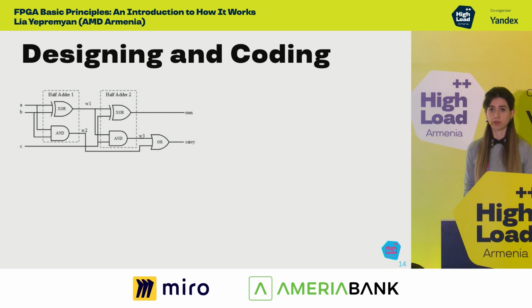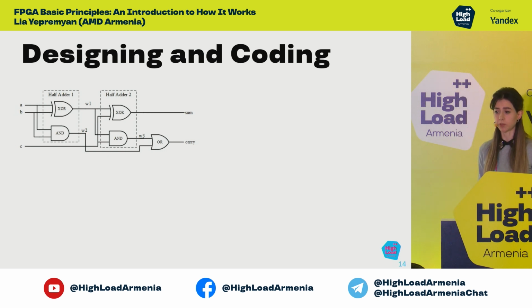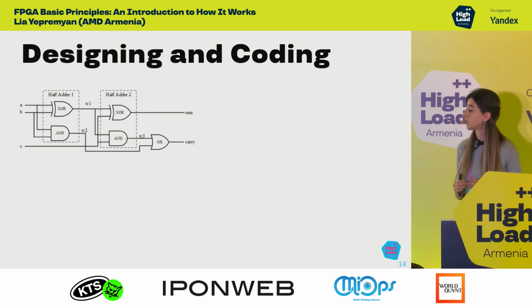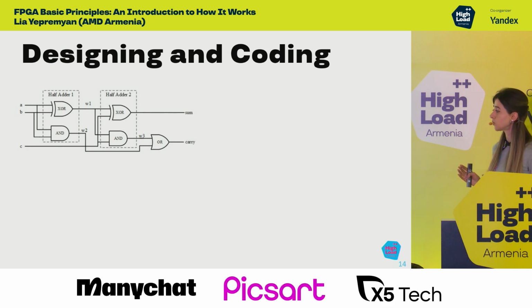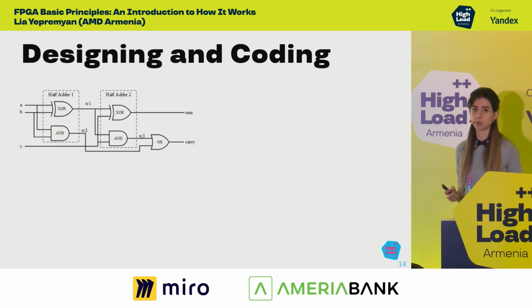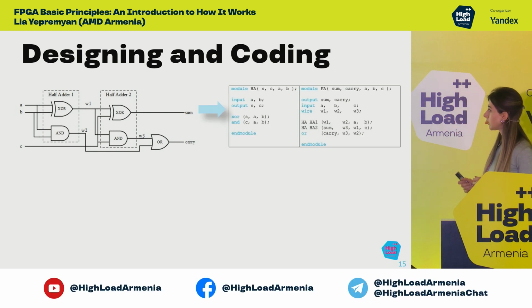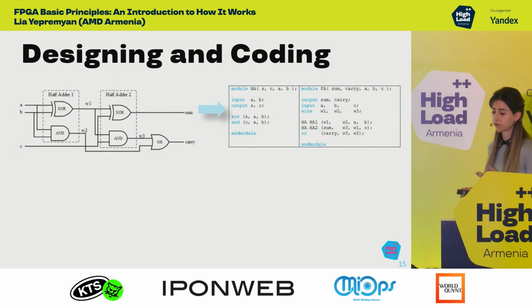The first phase of hardware design, whether ASIC or FPGA, starts with designing and verifying the whole process on paper before starting actual coding. In this phase, the whole design is broken down into different sub-modules. In our example, we have a 1-bit full adder, which is broken down into 2 modules, 2 half adders. When the design creation process is completed, we can write the code. The code, as we see, consists of the 2 sub-modules of half adders.